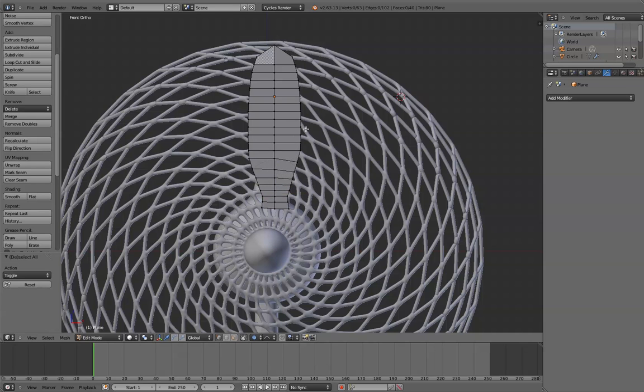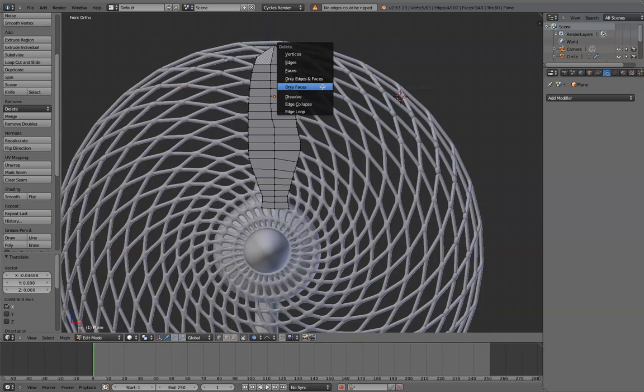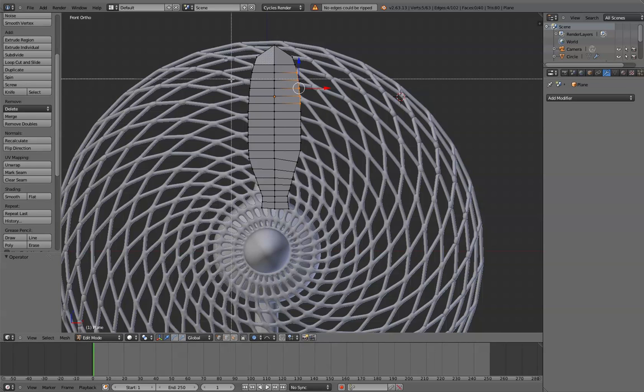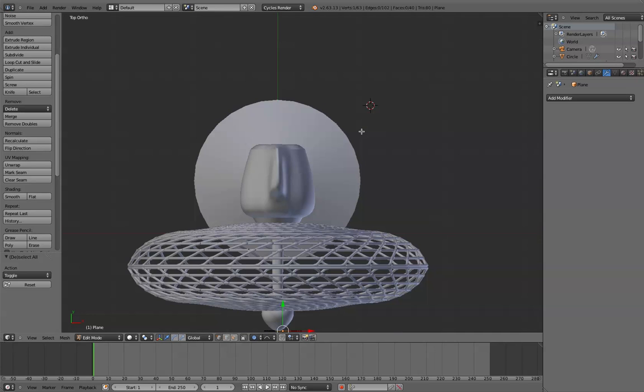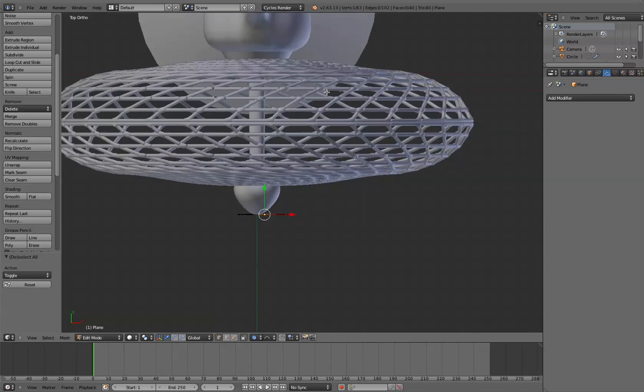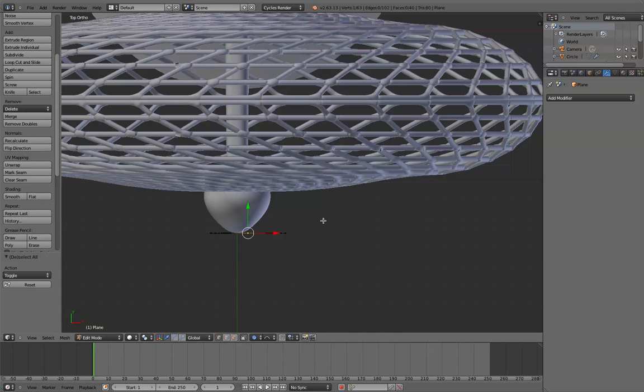Move in a little bit here. Maybe make it a little thinner at the top. Just doing that with really simply the scale multiplier. So what I'm going to do now is I'm going to just click this vert here, and I'm going to go into my top view, and with proportional editing enabled I'm just going to rotate and scale up and keep scaling up till I think